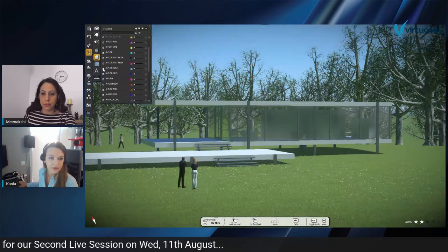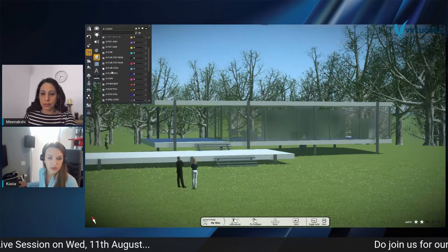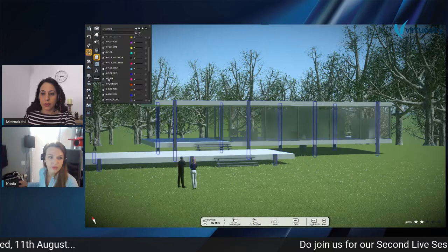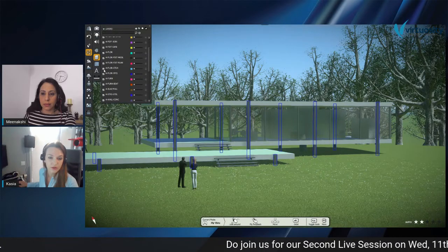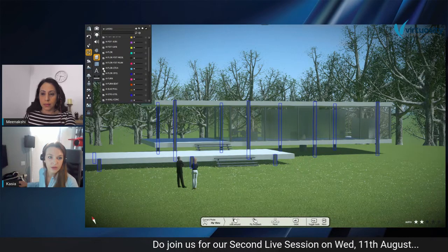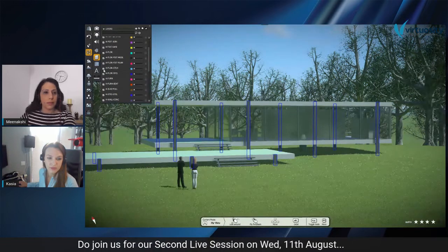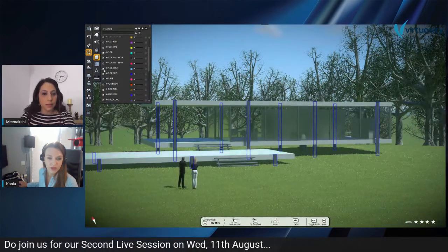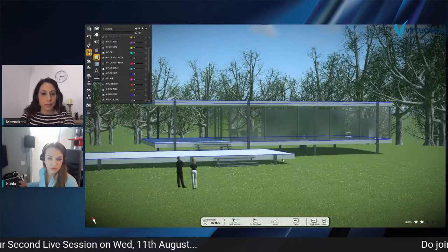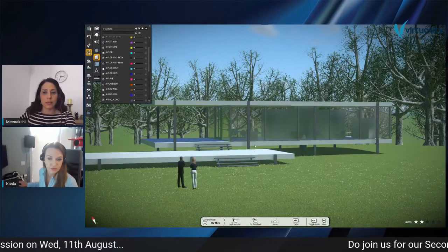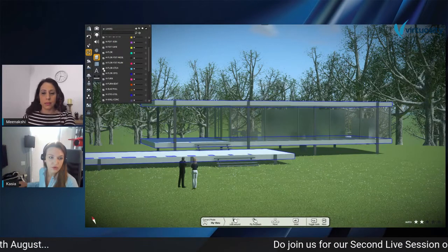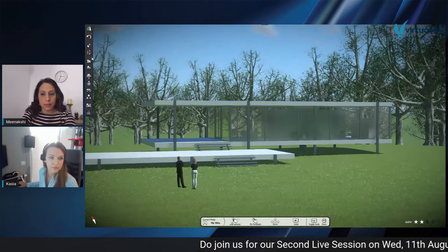You can see that the green surface appears on the deck of the building, and these are my spaces, architectural spaces that served me only for the drawing documentation for the architecture. So I don't need them, and I can switch it off in this tool.